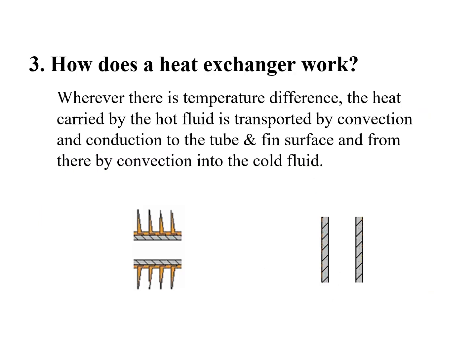Section 3. How does a heat exchanger work? There are three modes of heat transfer: conduction, convection, and radiation. The temperature difference between working fluids is the driving force for heat transfer. Whenever there is a temperature difference, the heat carried by the hot fluid is transported by convection and conduction to the tube and fin surface, and from there by convection into the cold fluid.